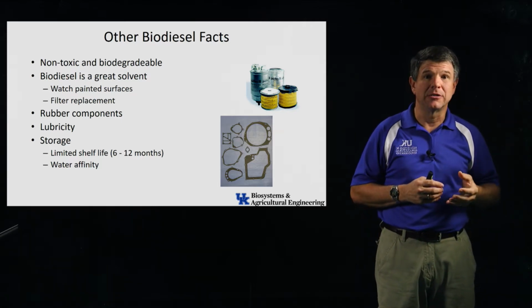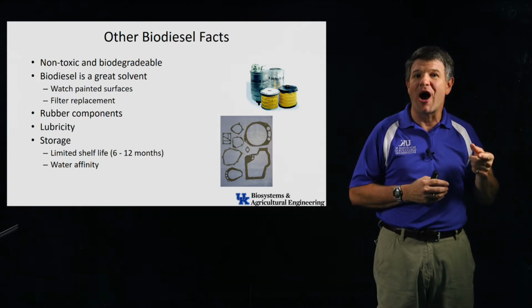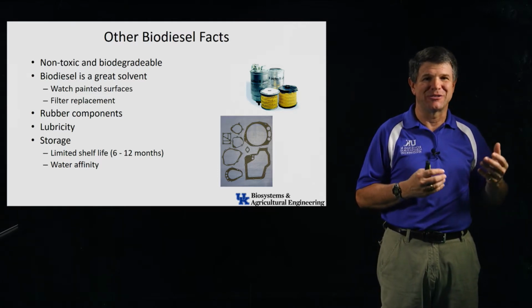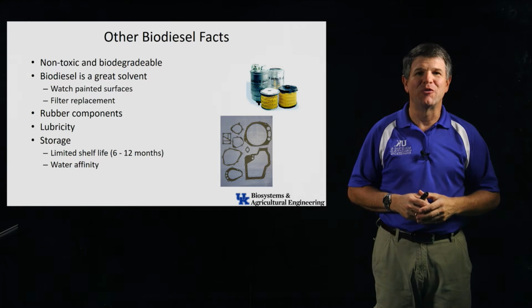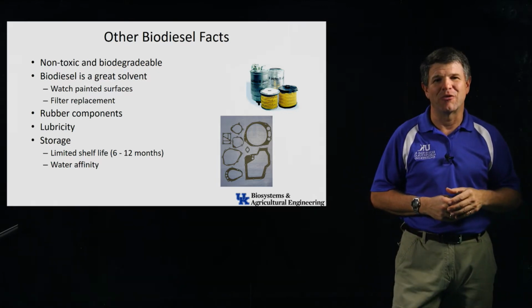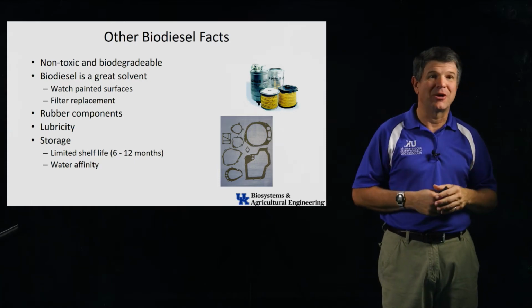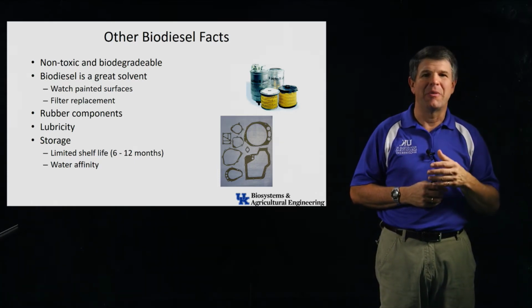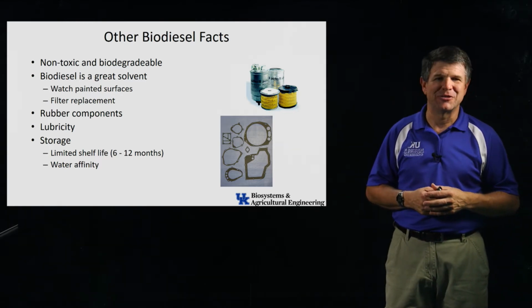You throw biodiesel in there, it's a solvent, so it takes all that wax and stuff off and it cleans it. So what was happening is we were cleaning the fuel system on this old vehicle basically, and all that stuff was ending up in the fuel filter. And so they had to replace 3 or 4 or 5 fuel filters before they got all that stuff cleaned out of the system. Once it was all cleaned out, then it was fine. But it was that paraffin, that waxy buildup that the biodiesel took off. So those are things that you have to think about, some odd things that you'll run into.